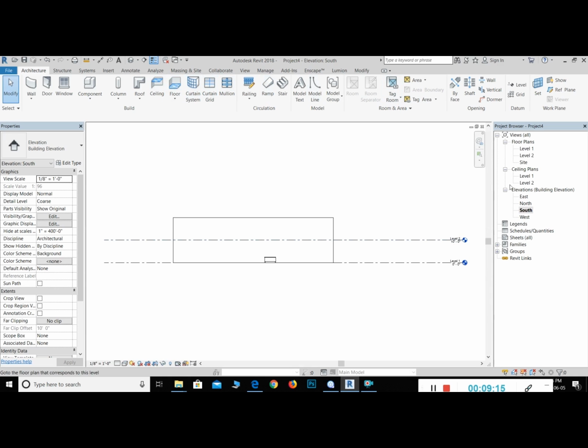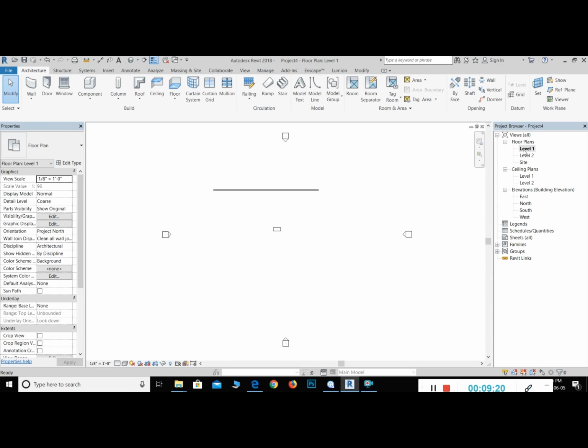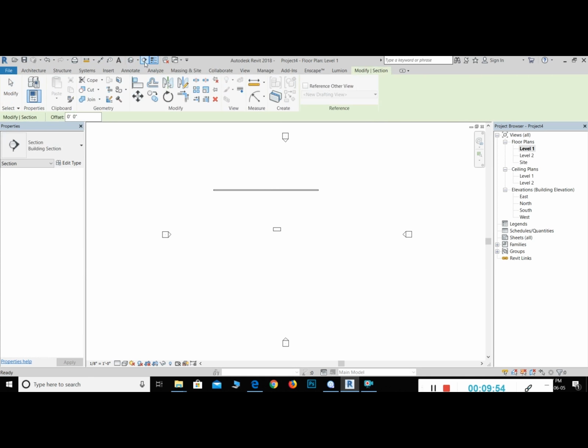but as you can see in here, there isn't any section. So how can we find it? If you want to show the section in here, you have to create the section. As a template, you don't have any section views in here until you draw them. So there are 2 other options to create the section. One is at the top, where you can see a bunch of tools that are very useful. So you can see it's in the section,